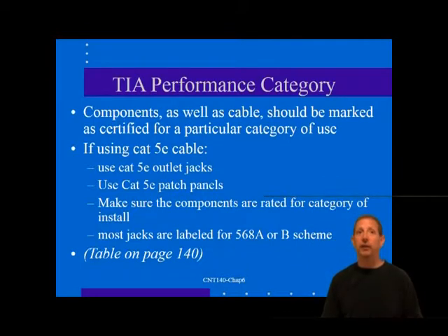The only practical way to increase data rates on unshielded twisted pair wiring beyond the current 1000 meg data rate is to use additional pair in a multiplexing or encoding scheme. Now this means that you can go to 1000 meg data rate without having to replace installed Cat5e cable links, which are nominally rated to 100 megahertz.